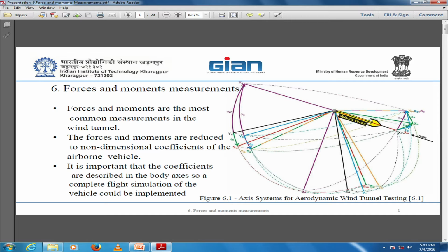Sir, how are you expressing the accuracy of balance calibration? We are talking about how you specify the accuracy of balance calibration. Formally, we are using the same definition as in any other calibration accuracy. Formally, the demand was 0.5% full scale. Today, it's decreasing to 0.1%, and I believe people will not commit to better than that.